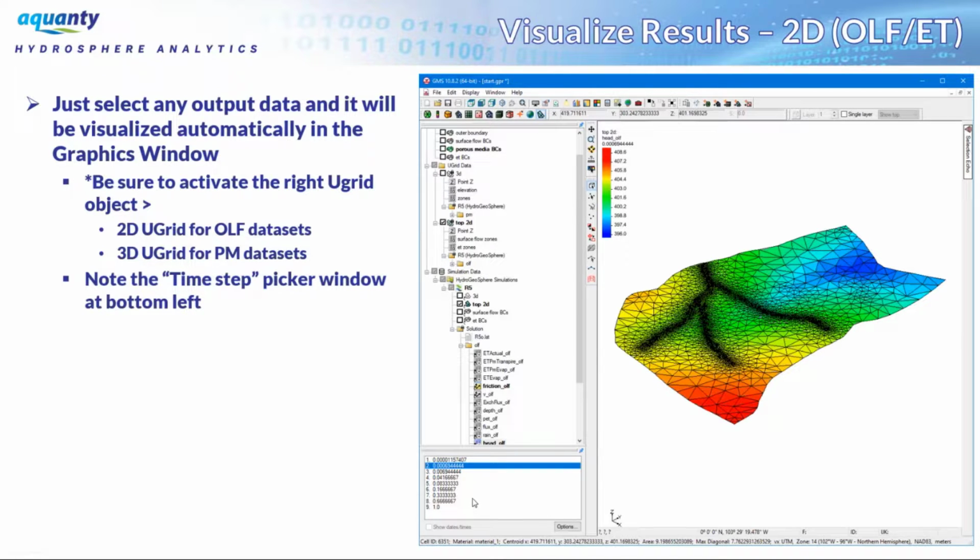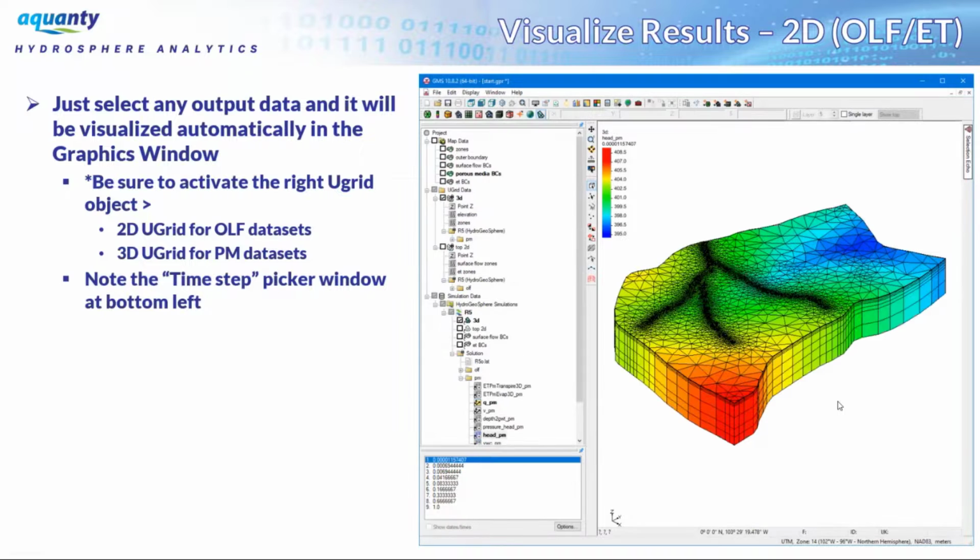There is a time step picker window at the bottom left here. So if you're running a transient solution that has output time, or many, many different output times, then those will all be listed down here in this time step picker window. So here we see an image of just basically a 2D data set, probably looks like heads throughout the overland flow domain or heads in the surface domain. And here we've got a 3D output. So this is heads throughout the subsurface.